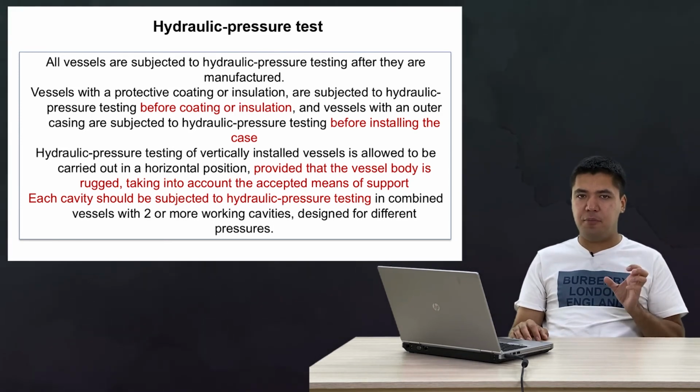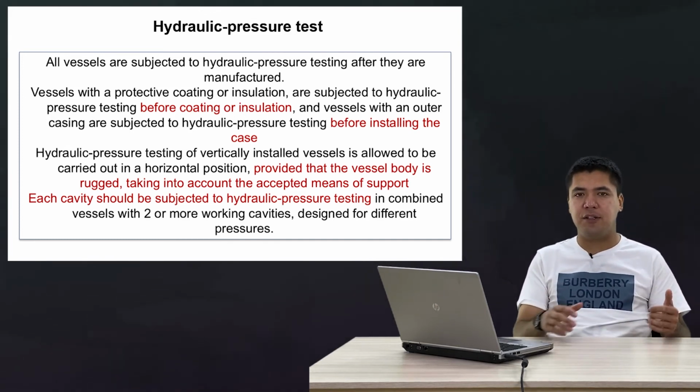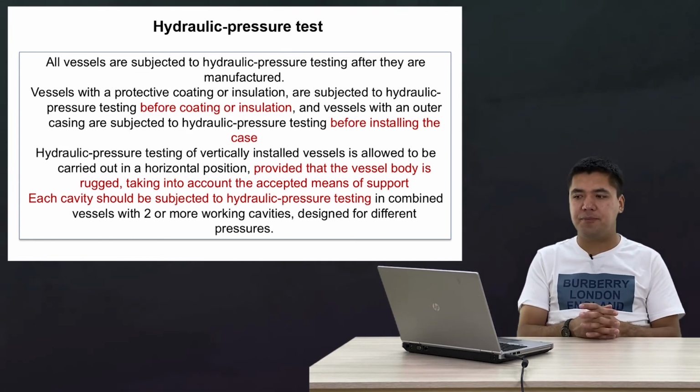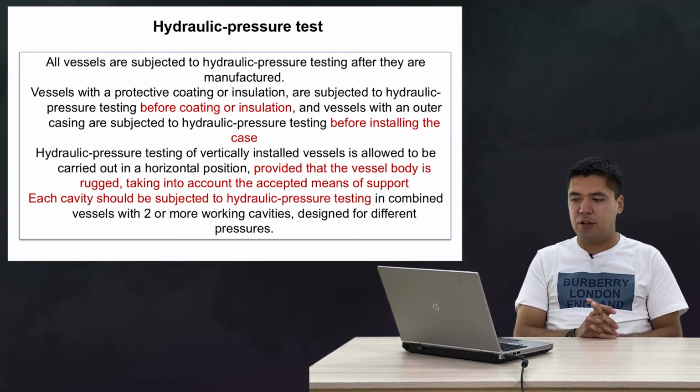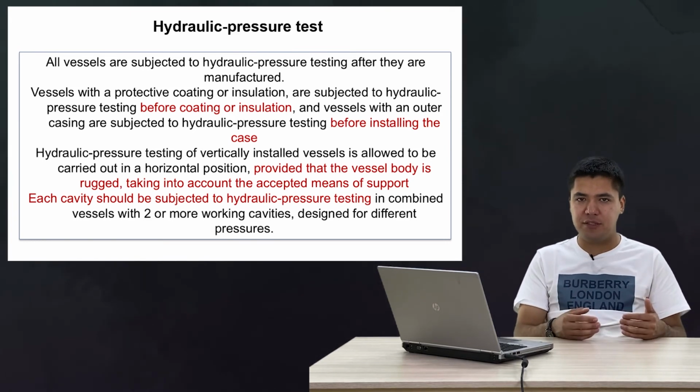And within the 5 minutes we can see where the water drips appearing or coming out. Like this, we can identify the defects of pressure vessels. And about the hydro test, we need to perform hydro test before putting any coating paint on pressure vessels.